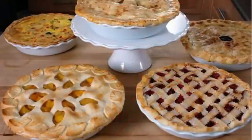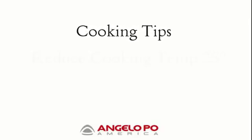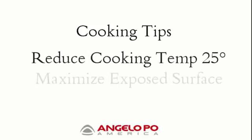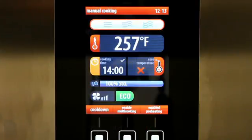The dry mode is recommended for items such as baked goods, oven frying, fast grilling of proteins, and other low moisture items. When using the dry mode in the Combistar oven, reduce your cooking temperatures for standard recipes by 25 degrees, maximize the exposed surface of food to be cooked for best results, and the recommended humidity levels are between 0 and 20%. Moist cooking is next.